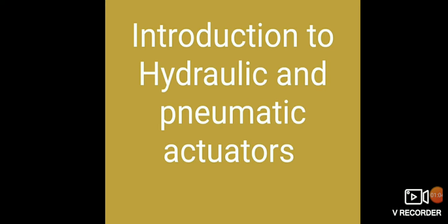An actuator is used to convert the energy of the fluid back into mechanical power. The amount of output power developed depends upon the flow rate, the pressure drop across the actuator and its overall efficiency. Thus, hydraulic actuators are devices used to convert the pressure energy of the fluid into mechanical energy, depending upon the stage of actuation.